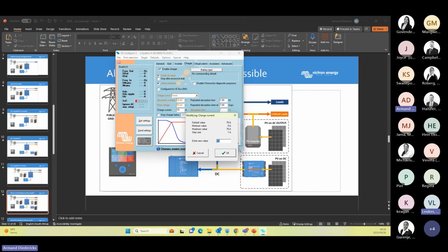That's on a three-phase scenario, especially if it goes higher than three-phase, or it stays three-phase and you've got 6 inverters. Take the total charging requirement divided by 6 inverters, and then each inverter has the specific charging current that it needs to provide. Otherwise, you'll overcharge the battery, and there will be differences and all sorts of problems. So charging depends on what size the battery is.